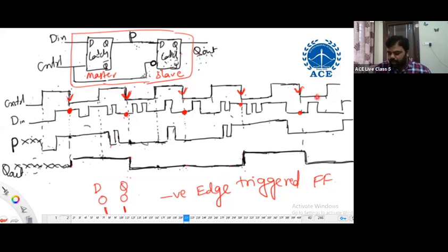Yes. So what we have been saying is, while drawing inputs itself, I mentioned don't change your D input while control is changing from 0 to 1 or 1 to 0. Why? What happens if I change? What we discussed here, so this construction is becoming a negative edge triggered flip flop. At this negative edge, we are observing logic 1 enable latch is getting disabled. Logic 0 enable latch is getting enabled.